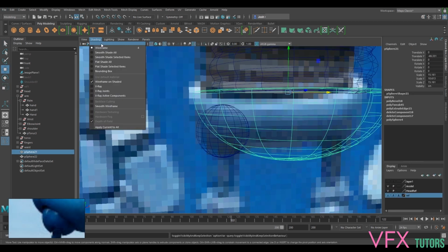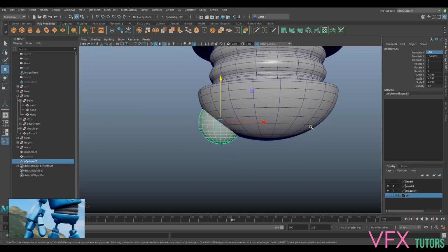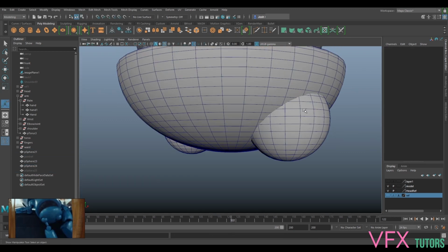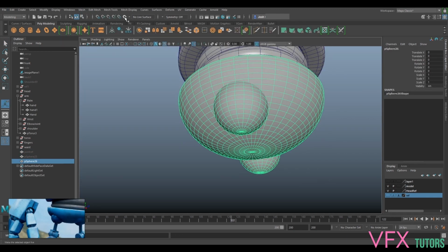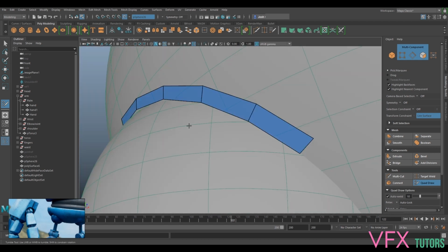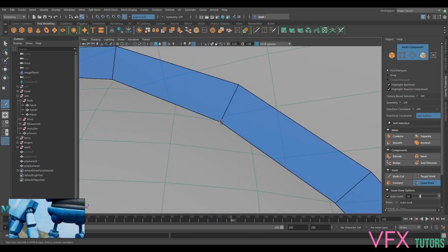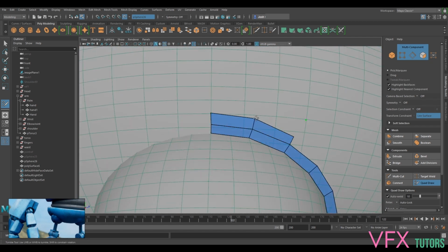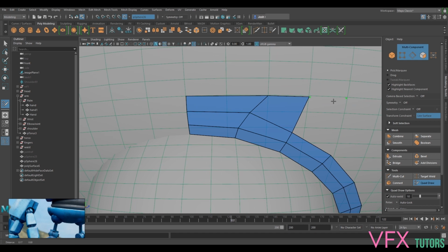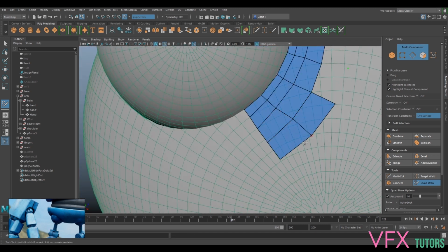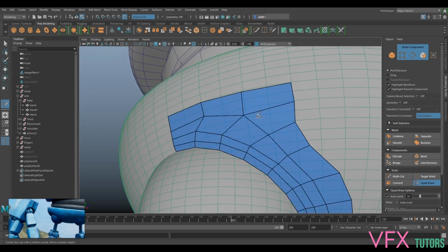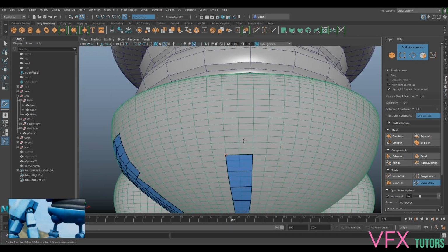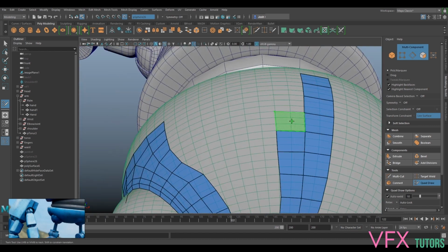This will be another example of modelling to a high-res base mesh using quad draw. So I'm just using these round objects and the half sphere, subdividing them enough so they're smooth, and quad drawing the actual shape I want. This looks like a lot, but you only have to do a quarter because you can duplicate the rest. If you've got a quarter done correctly, it makes everything so much easier. You don't have to worry about the rest.